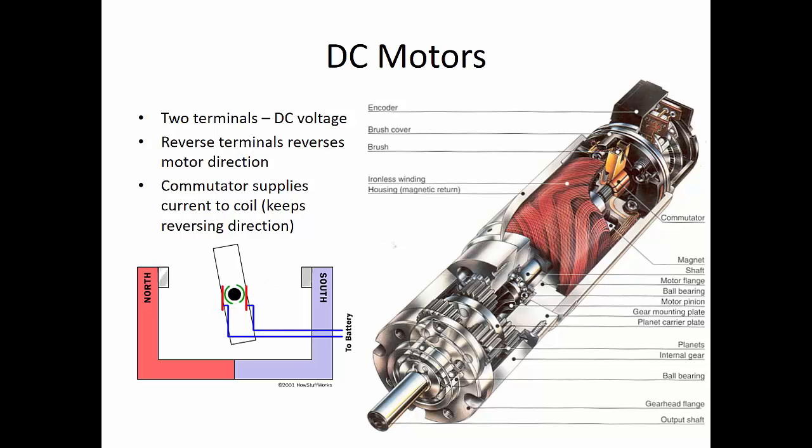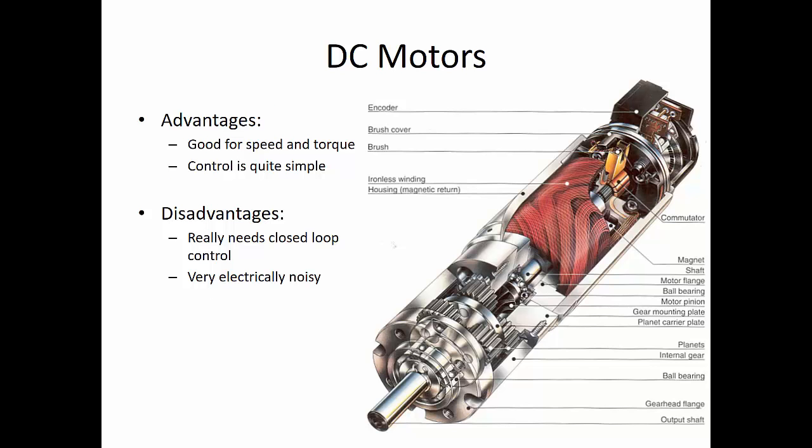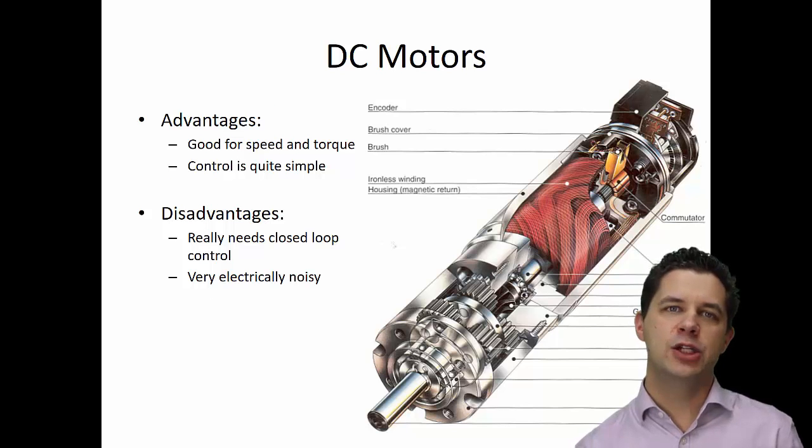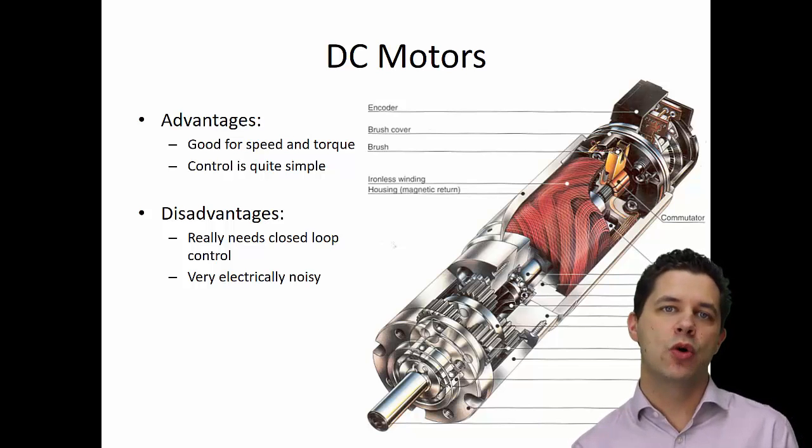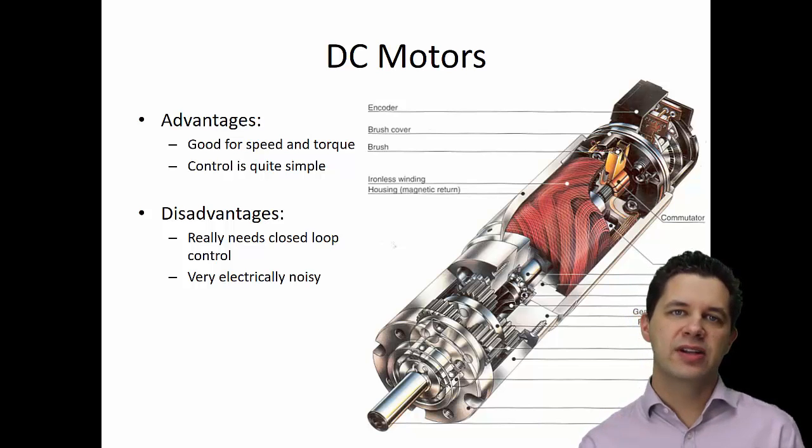This sort of DC motor, and we see a very sophisticated example of one there, with gearboxes and feedback associated with it as well. It's the sort of thing that we find in a wide variety of applications. Everything from cordless drills through to kids' toys and things like that. Whole range of different DC motors that allow us to power things just with these two different terminals, and we control the polarity and the amount of current that we pass into these to control the speed and torque associated with them.